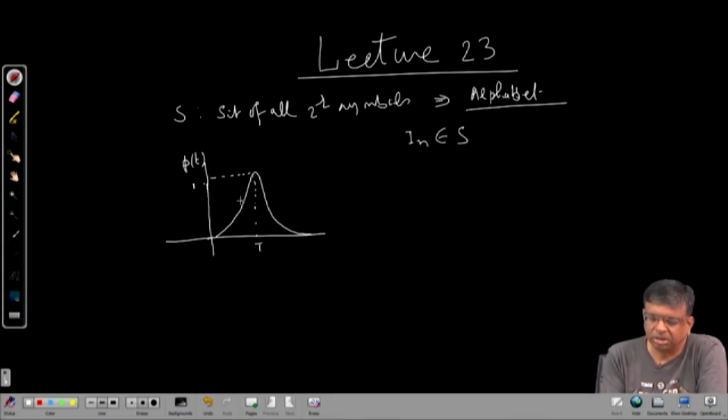The pulse remains as it is, its height will be multiplied by I0 into 1, so I0. Then you trigger the same pulse after some time, maybe tau, and that will be multiplied by the next symbol I1. Then after 2 tau another pulse will be triggered and multiplied by I2, and like that, and through the channel the superimposition of these pulses will propagate.